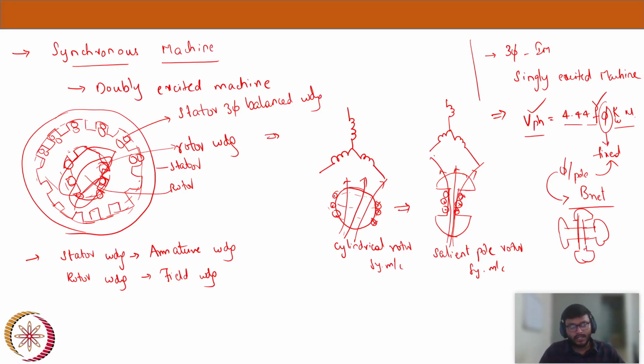During light load condition, it's a very poor power factor. Now, why would anyone want a machine to work at a very low power factor, especially at high ratings? If it is a large size induction machine, there will be a large magnetizing current drawn by it. So people don't go for high rated induction machines for a three phase system.